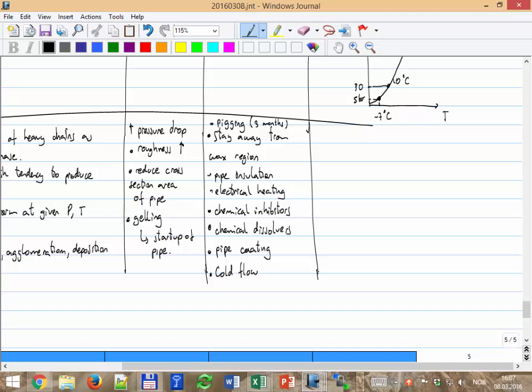Yes? It's about coating. So coating is outside, insulation is inside? No, coating is inside of the pipe. And what's the difference between insulation and coating? If you have your pipe like that, coating goes here. It's a small layer that you put and you cover, on top of the inner part of the pipe. Insulation, like you saw on the thing that I passed, is outside of the pipe.